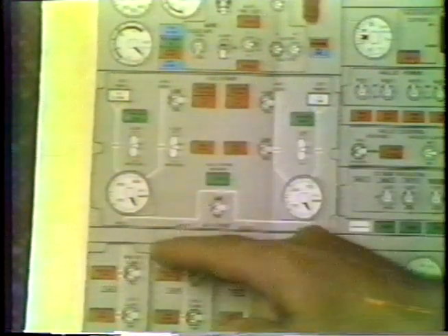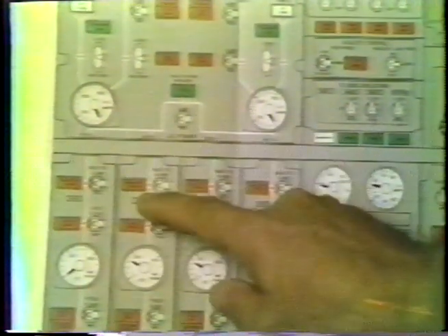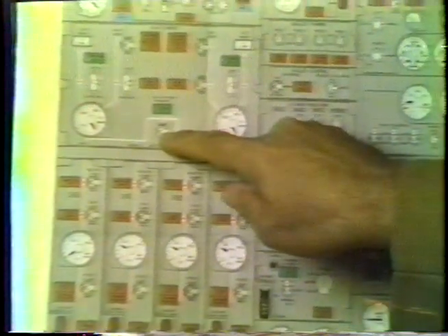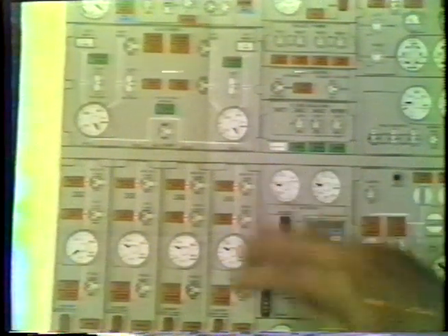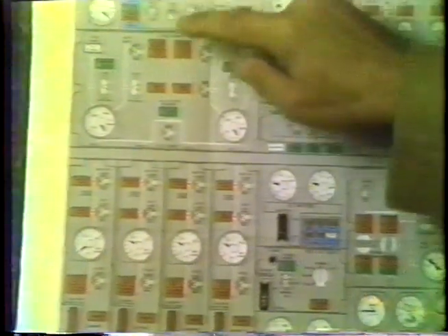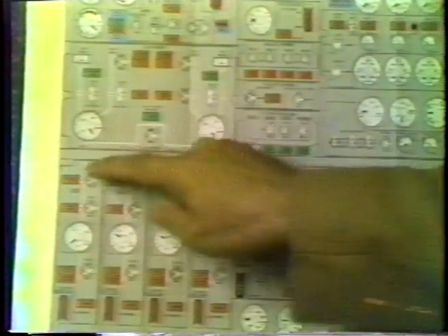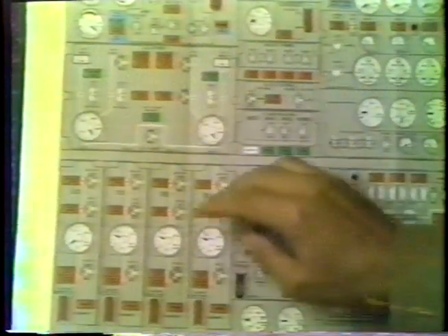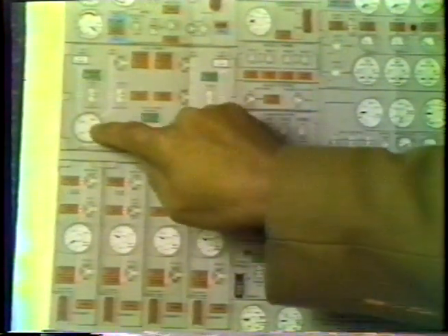Now, using number 1, power will be immediately applied to bus number 1 and bus number 2. However, if this split system breaker is open, green light on, power will not be on bus number 3, number 4, and essential power. So applying ground power, make sure the voltage and frequency is correct, and bus tie breakers are closed, and the split system breaker can be closed. Now, the amount of power that's being used by ground can be measured in amps with this meter.